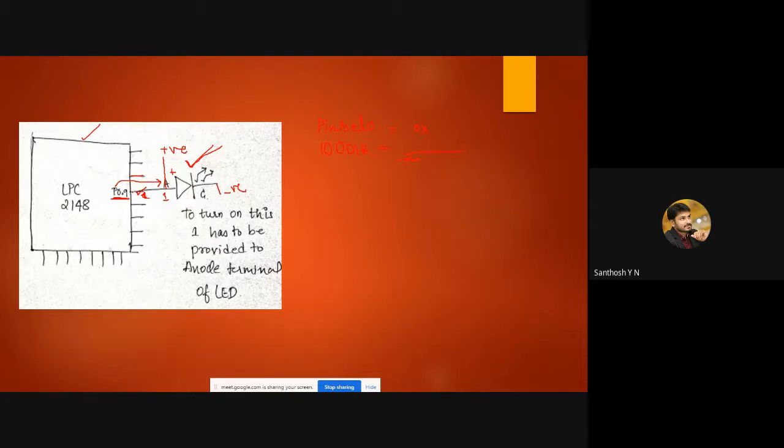So if I want to make this pin go high, which register will you use, IO0 set or IO0 clear? Tell something. Only two registers are there. Whether you'll go for set or clear. Set, sir. Yes, you have to go for set. See, to get the answer of a single word, I have to shout so much. You are giving set, clear, like that. Anyway, be active.